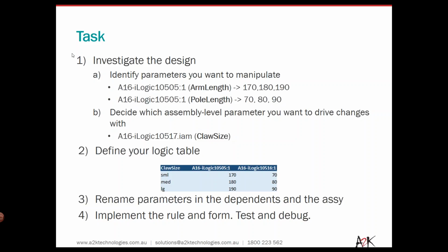change. So when you're first planning iLogic, you have to investigate your design. After you've investigated this design, we then define this into a logic table. Okay, I really encourage you to do this, to actually specify each of those changes into a bit of a spreadsheet, or even just write it down.